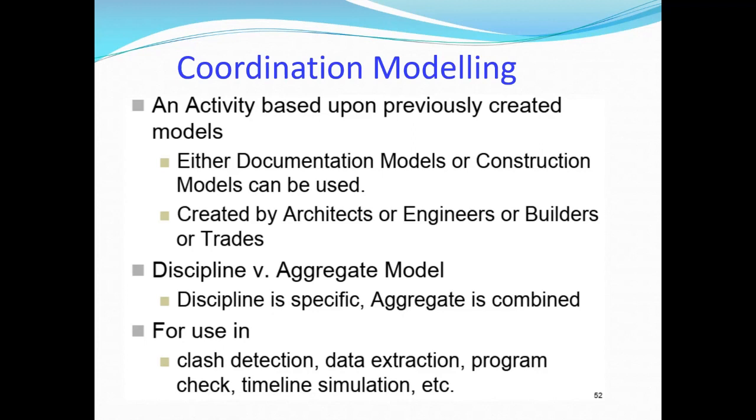What they do is coordinate the different trades and do clash detection. Is there any clash or not? Sometimes our beams and MEP may clash. Sometimes our beam-to-floor headroom is not sufficient, because the architect may not think about the beam, so they may not have enough headroom. These are the clashes we can detect earlier. That's the purpose: to coordinate all trades into one model.